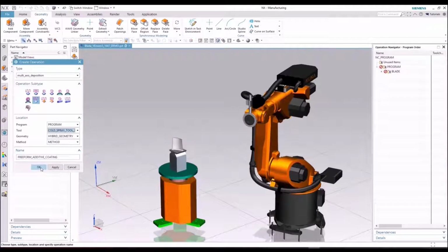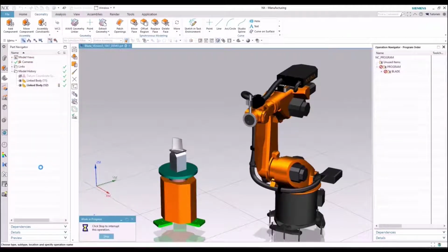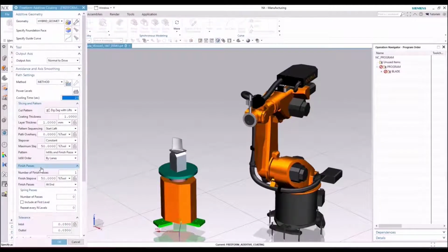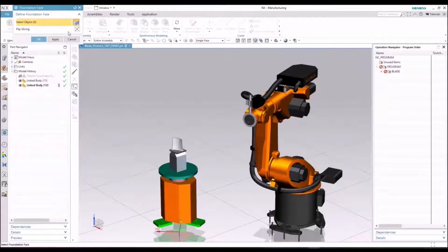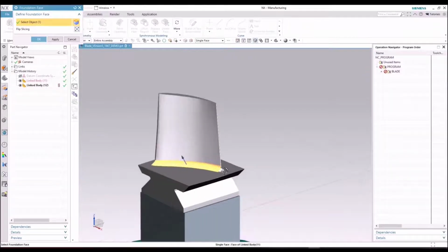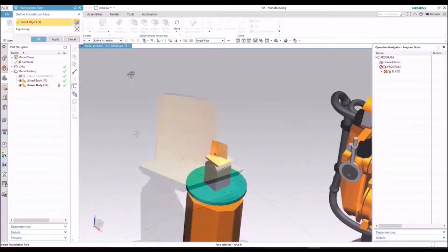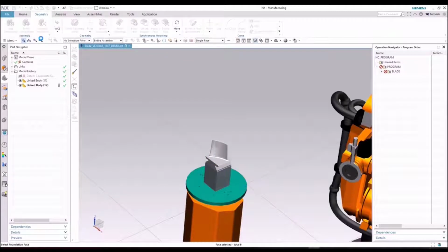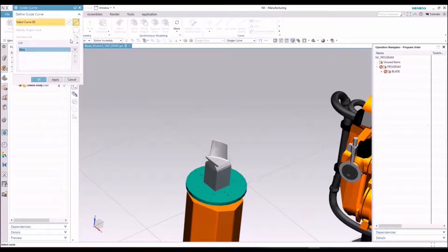In order to calculate paths along which the tool is to be moved, affected surfaces and guide curves need to be defined. The selection of surfaces is possible by different methods, such as specifying single surfaces or tangential surfaces. To allow for correct tool movement, ensure positive orientation of all contiguous surfaces by picking the correct orientation of their normal vectors outward. As for surface selection, there are various possibilities to select the guide curves.